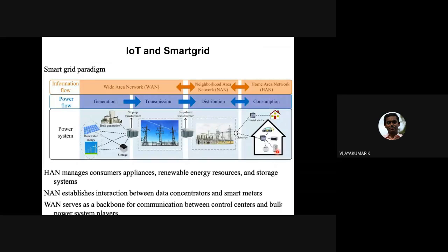For your demand response management algorithms, we can use these thermal storage loads. Even the air conditioner is the same. Instead of 20 degrees centigrade, you can make it 18 degrees centigrade, so we are storing the energy in the form of cooling. So this is a thermal load, and I always look at it as a thermal load. Even one of my scholars is working to aggregate these thermal loads in a high-rise building so that you can reduce the battery size in microgrids, right?